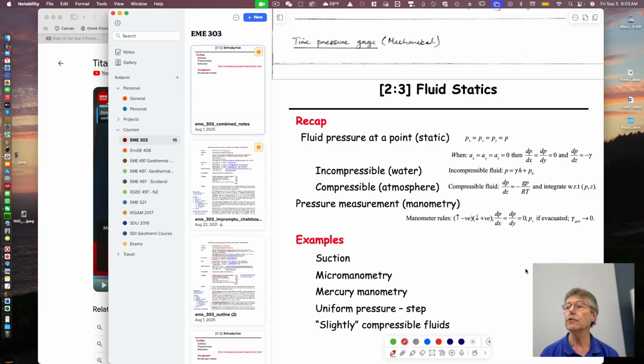If you fly in a plane, out of State College, we talked the first time about pitot tubes. If you go up to the plane and look just below the pilot's location in the cockpit, there's always a little pitot tube facing forwards. It measures the pressure of air being pushed against it versus the pressure of air just at that elevation. And by subtracting those two, you can calculate airspeed.